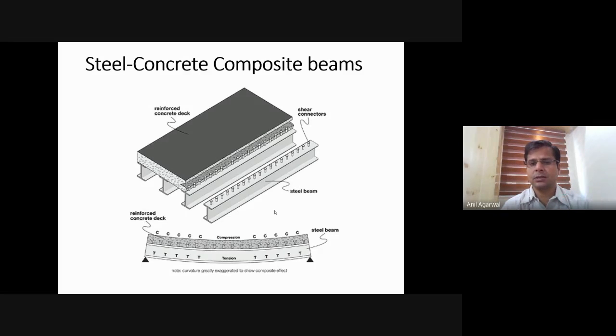Shear studs look almost like a bolt. They are very effective, and they are much faster to weld. You can go to the internet and see how they are welded. This welding process is very fast; they can weld one shear connector within 10 seconds or so, and they already have pre-marked locations. One person goes with a kind of gun which has all the shear connectors stored, or puts the shear connector in from outside and connects it, and it immediately gets fused through the steel deck and goes and fuses with the top flange. But there are other options. Not everybody has that kind of infrastructure, so sometimes they go with regular traditional arc welding, and they use channel sections also.